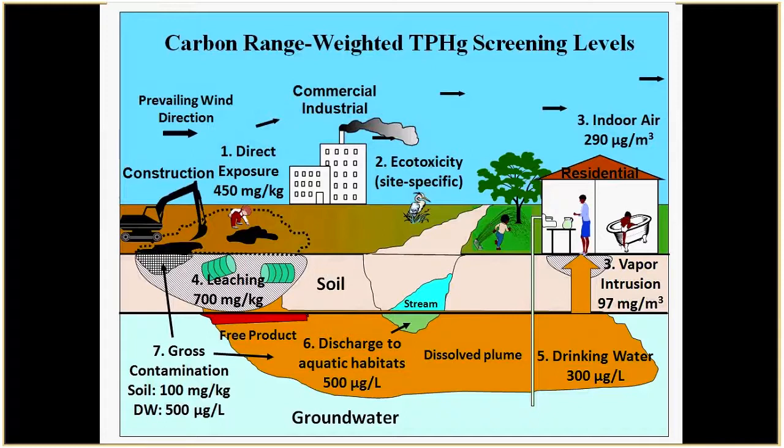And so in this case, you probably wouldn't want soil with 450 ppm gasoline in it in your backyard or in your playground. You'd definitely be able to smell that in the soil. Now, in theory, that doesn't pose a long-term health risk for kids playing in the soil, but you would definitely notice it. It's just going to cause some other problems. And if you dug into this soil, if it was buried deep, you're going to get a sudden emission of vapors that could pose short-term problems. And you can do the same thing for groundwater. Well, this all gets pretty complicated, lots and lots of numbers. I know I overwhelmed people in part 1 of the webinar with all these numbers and details.